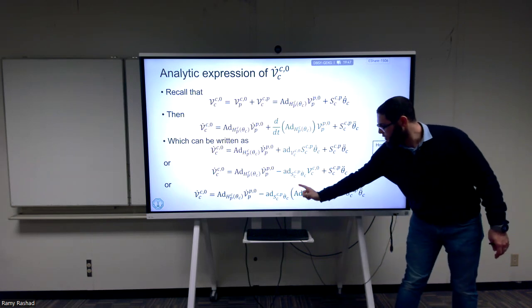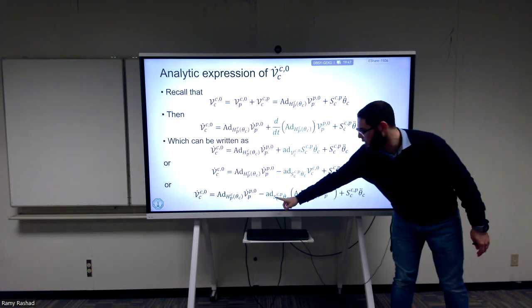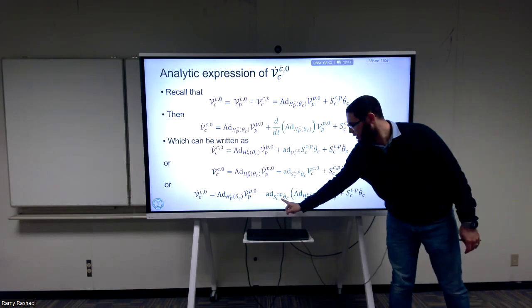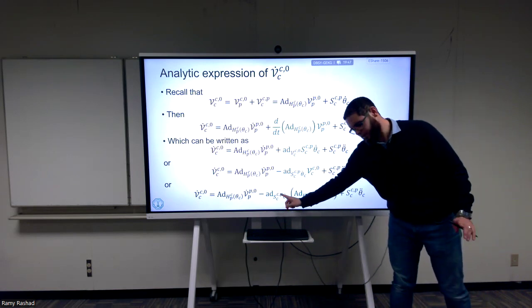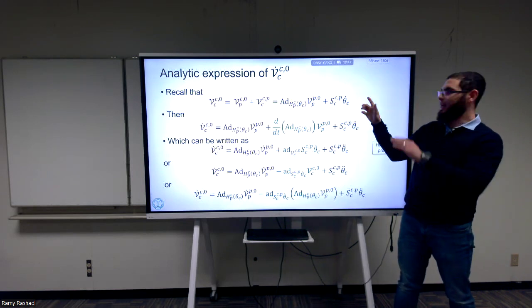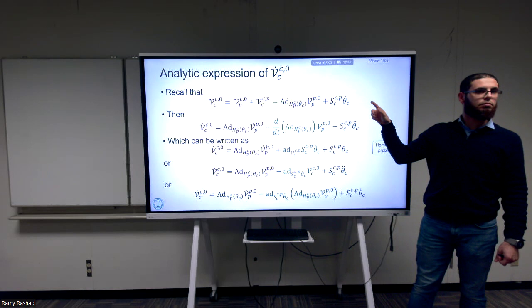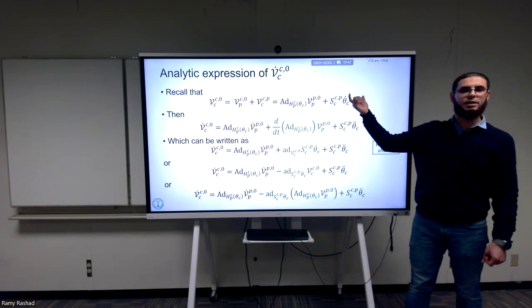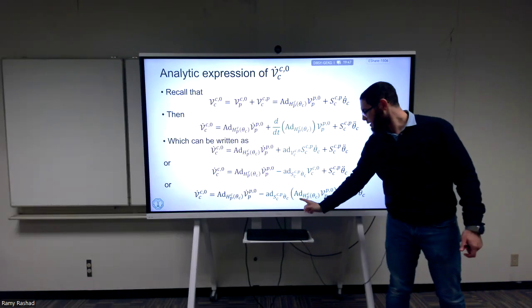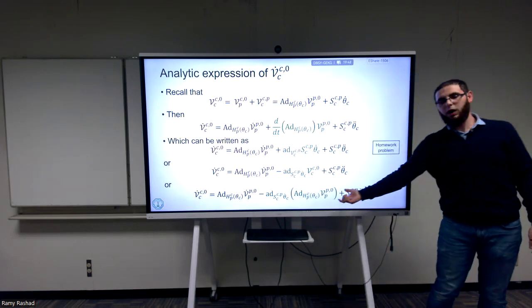Only the adjoint of the second one, which is this term, is the one that remains, while the adjoint of that one, this one with respect to this one, is equal to 0. Can anyone see why? Why is the adjoint of the CPC multiplied by theta dot, when you take the adjoint of this term, you get 0? Because it's the same twist, right? In the end, it's the same twist. So actually, this term is VCPC, and this term is also VCPC. So in the end, they just cancel out. Okay? So this is why we get this term in the end.